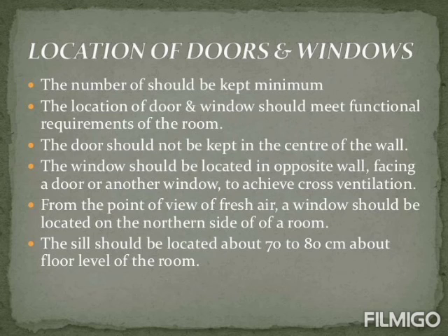Now let us look at where exactly the doors and windows are located. The number of doors and windows should be kept minimum. The location of doors and windows should meet functional requirements of the particular room. The door should not be kept in the center of the wall.